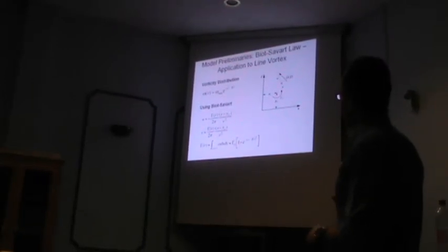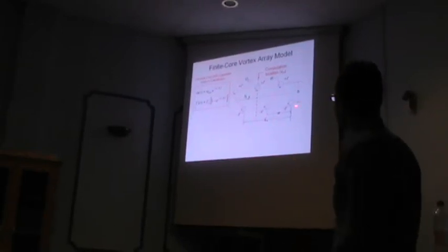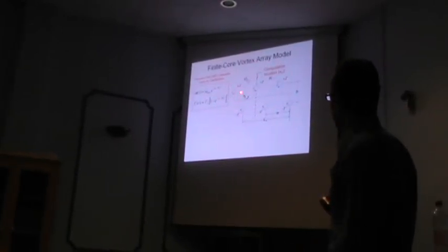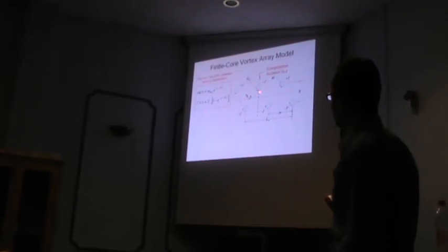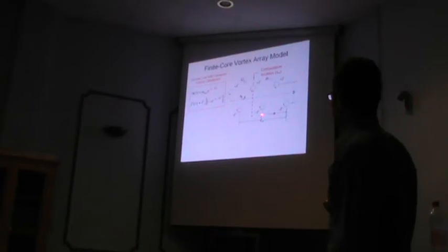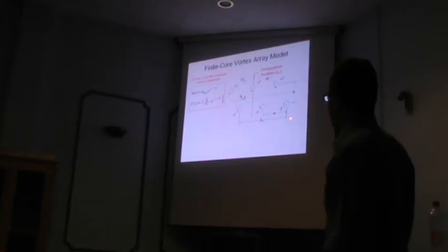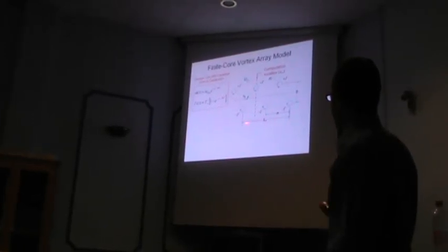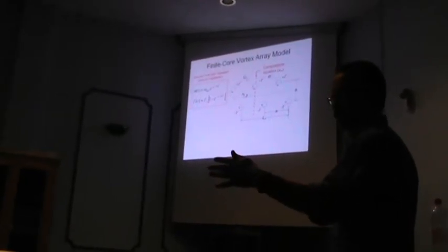Okay, now that we have this, we can extend the model into an array of vortex structures as shown over here. And as you can see, this is consistent with the flow visualization that we saw, where we have the counter-rotating vortex pairs, the parameters A, B, gamma, the core radius. One choice we actually need to make is the length of this array. How many vortex pairs do we need to include in the model?